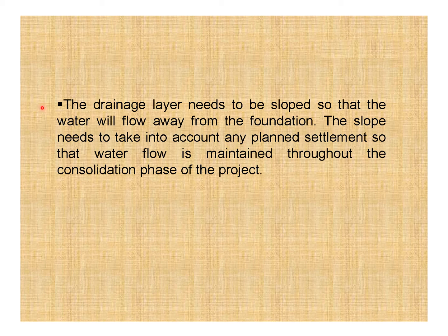The drainage layer needs to be sloped so that the water will flow away from the foundation. The slope needs to take into account any planned settlement so that water flow is maintained throughout the consolidation phase of the project.